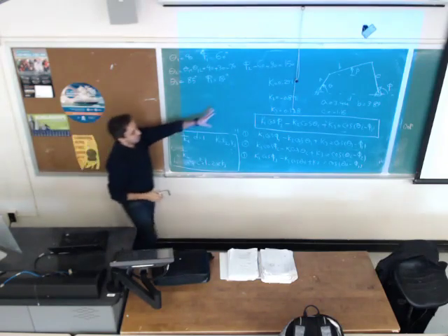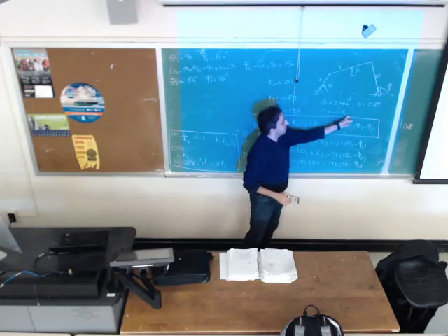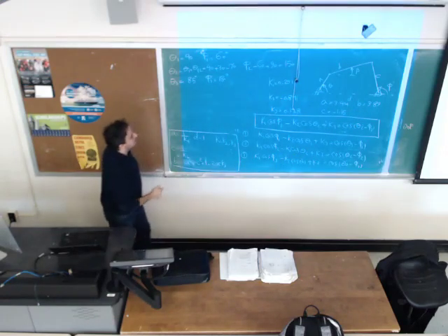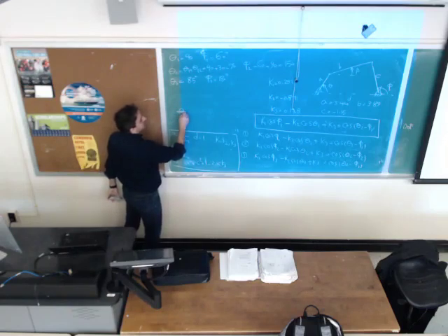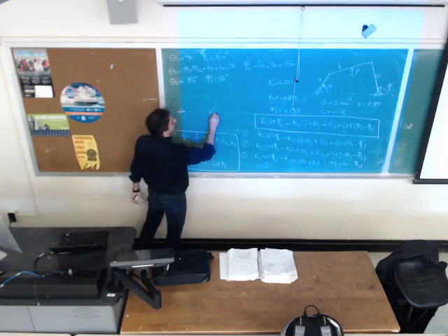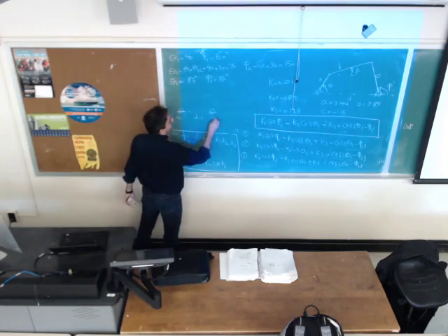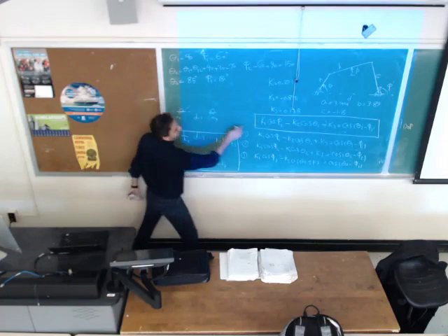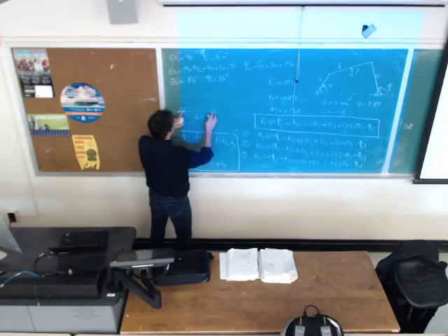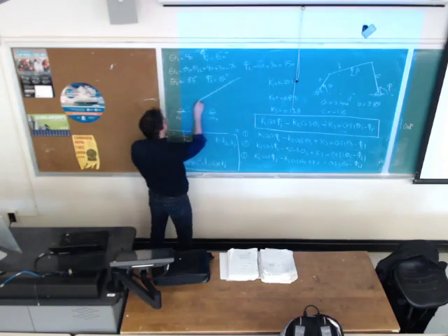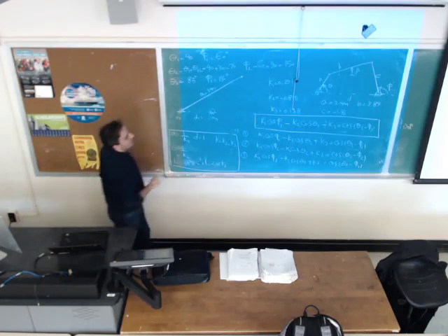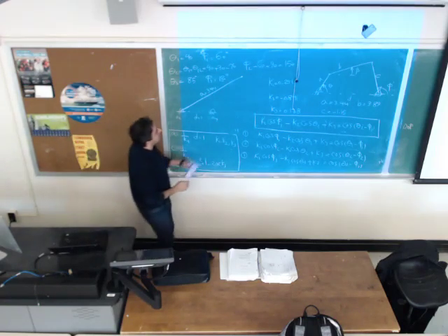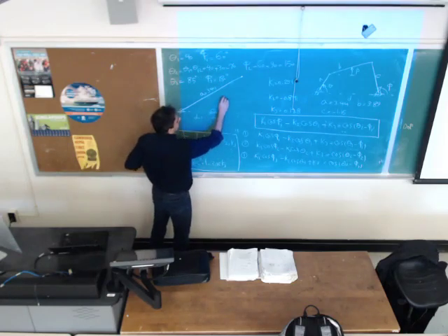So in this problem, we got a positive value for A, a negative value for C, and a positive value for B. We cannot have a negative value for an angle. So you start drawing the mechanism. D is 1, so I put D here, O2, O4. Theta 1 is 40 degrees. The length of A is 3.4, somewhere here. B is... Phi 1 is 60 degrees.